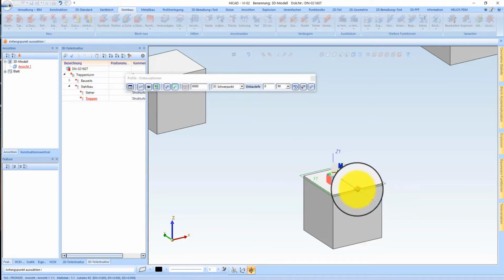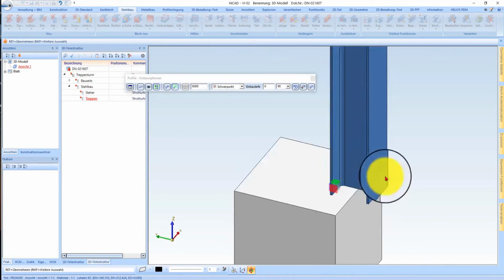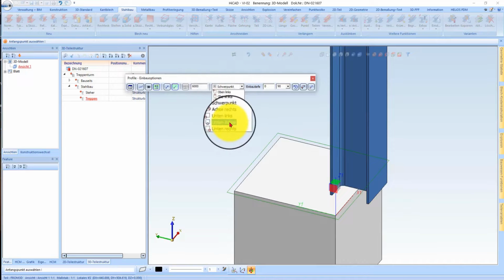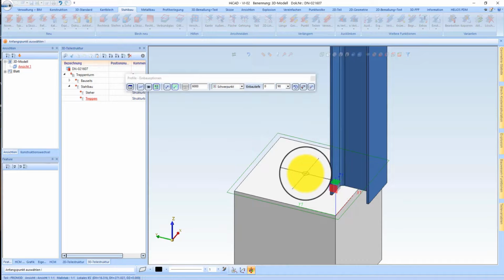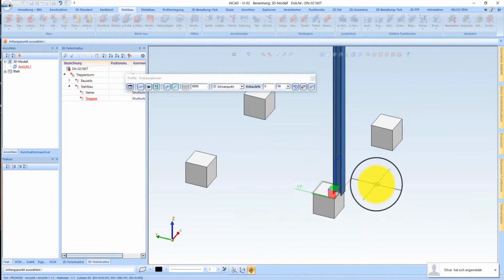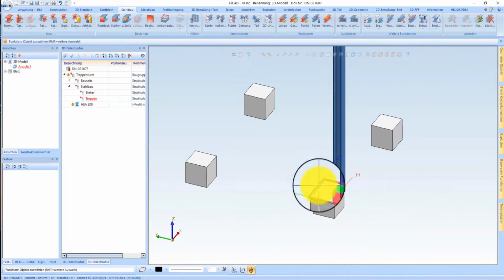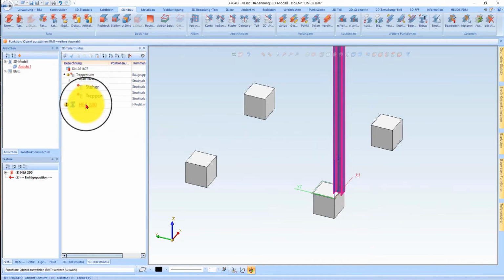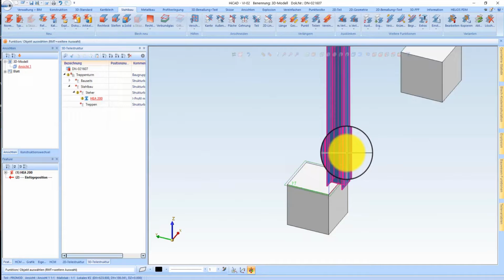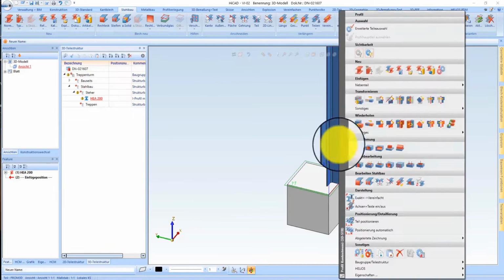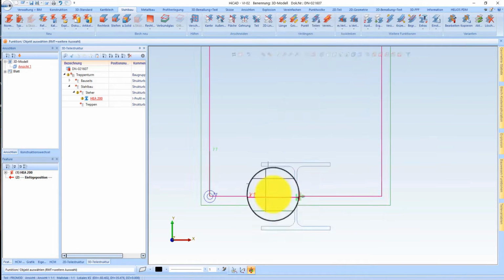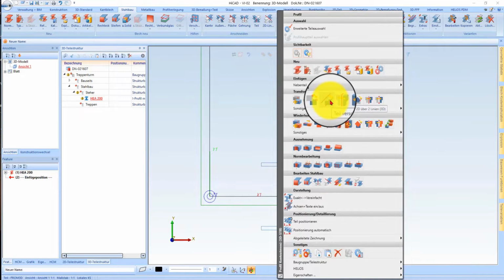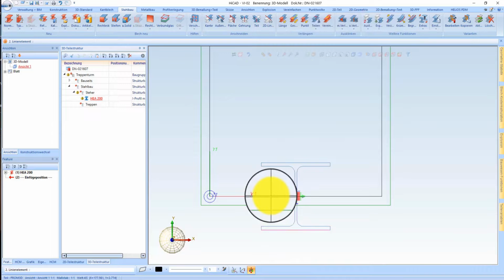this one here, on top. So I could again work with this by saying, for example, the bottom axis. But as I said, for me, it is always important that people get the parts to where they need to go. So that means I will naturally pull this right in and can of course work with the copy functions, move functions, and everything else. That means I will simply move this beam into, or I go into the top view and move the beam to the correct position. That means I use this D move a lot over 2 lines, from edge to edge.